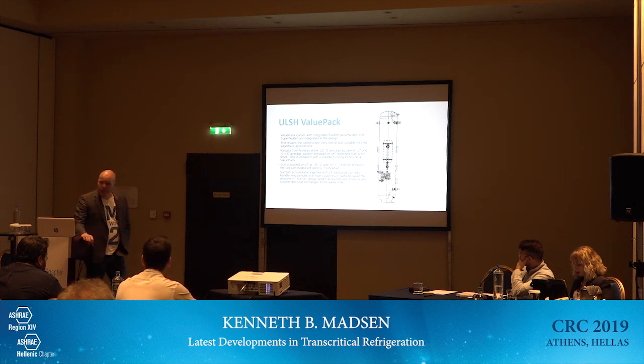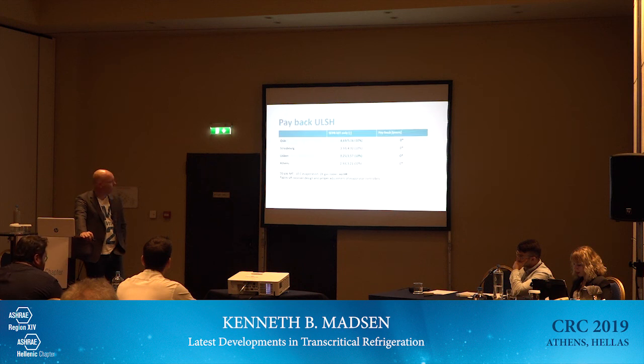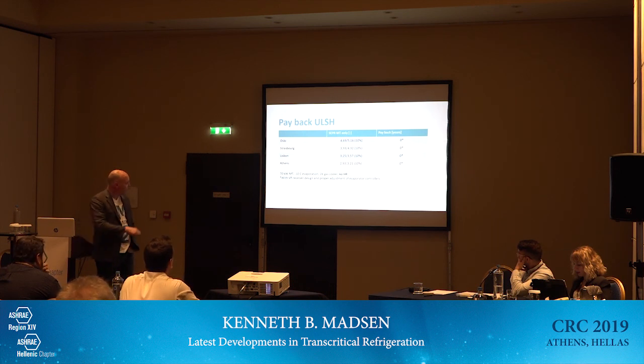So enough about low superheat, but there's a potential saving here. Usually we say that it's around 10%, and then my contractors say that 10% is not enough. It's more than that, but it is in that range. If you look at the payback time on the smaller ones, you can see the saving here is around 10%, and here it really doesn't matter where we are placed, because this is an evaporator thing. It has nothing to do with the ambient. So the saving, no matter where we put it, is basically the same.